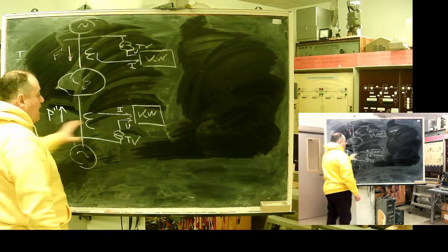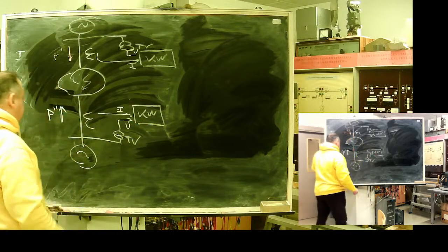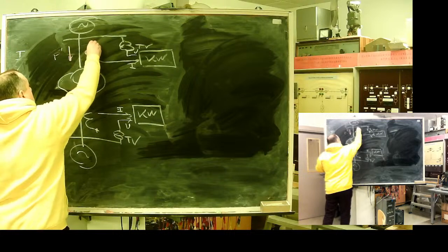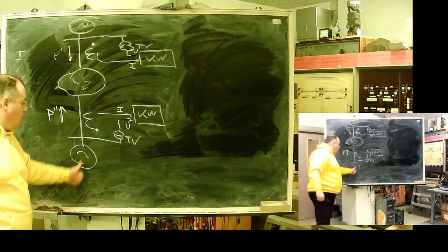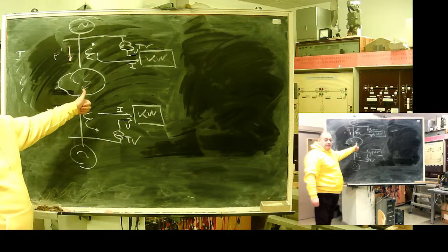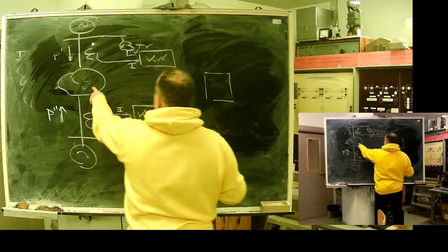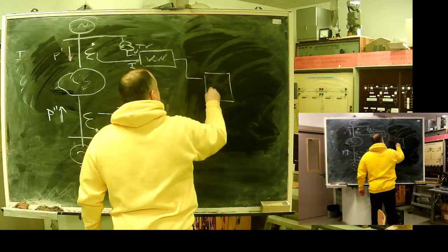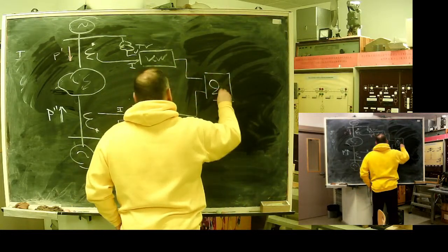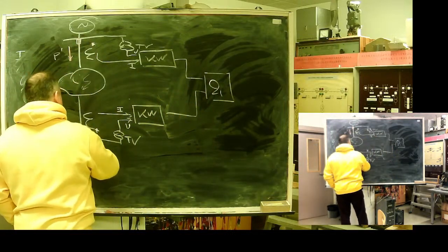So, if I have for these relays a characteristic, if power flows from the bus towards the load, in case of an internal fault both will show positive 1, and I need to disconnect the switches, these are circuit breakers.